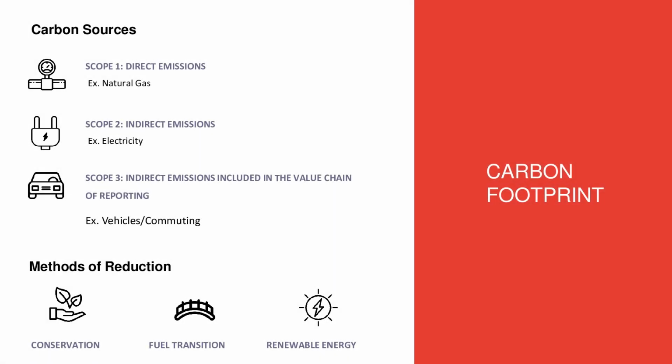In terms of general strategy, the most important approach is conservation first. So whatever you can do to use less energy first is best value. That can be things like retrofitting of your building envelope, changing the set point on your thermostat depending on the occupancy of your home or otherwise at certain times of day. Having a little bit of automation on your lighting potentially. So anything you can do to conserve energy first is most important.